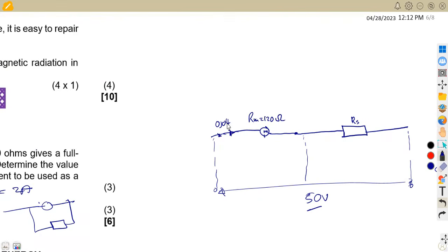The 0.04 is the same current that is going to flow, because it's in series, so you're going to have the same current throughout. This is the current through the series resistor, and it is also the current that is affecting our meter. So it's the same current. The question is asking you to calculate this resistor. So how can we do this?